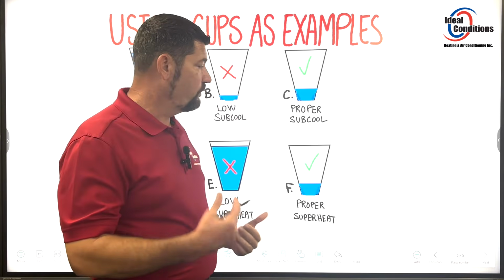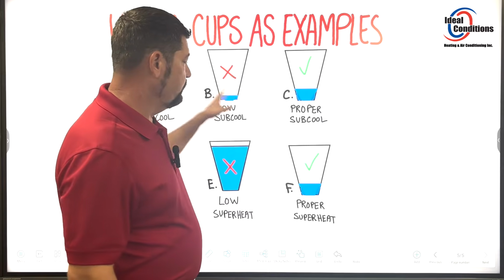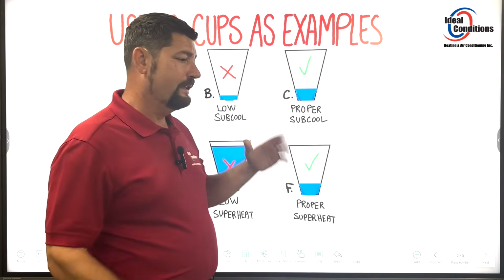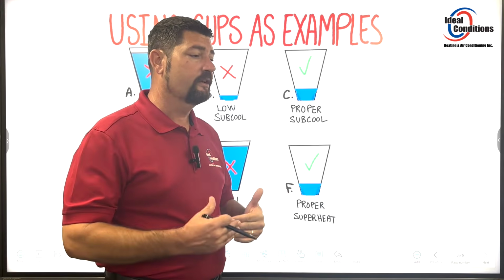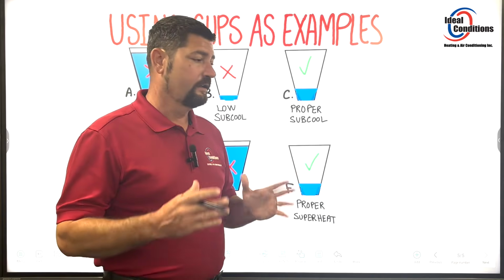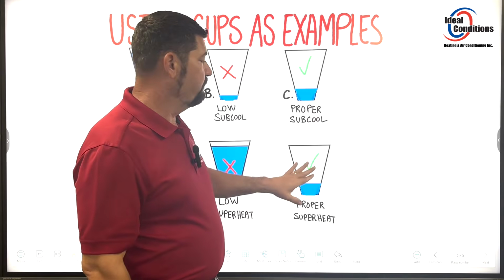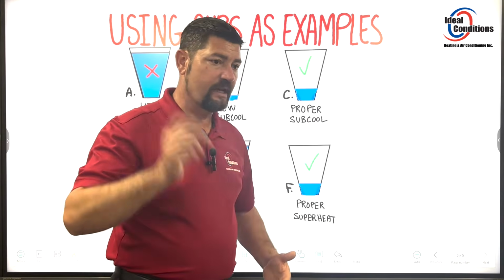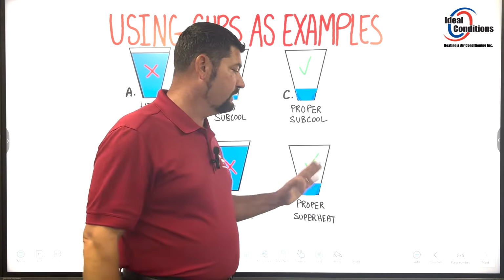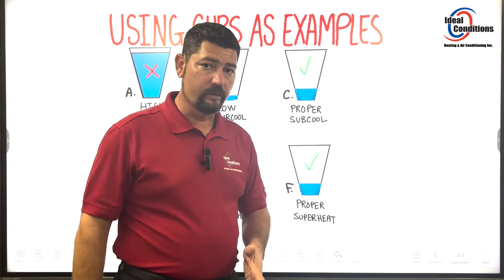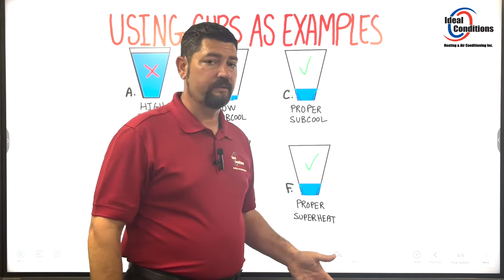Okay? And so if we have a good ratio with a bad ratio, and that does not add up, it's because something is not right. And so you will never be in that situation where you can check that box and say there's not a problem. If you are in that situation, most likely you have dirty coils or you have a bad pumping ratio. There's something there.